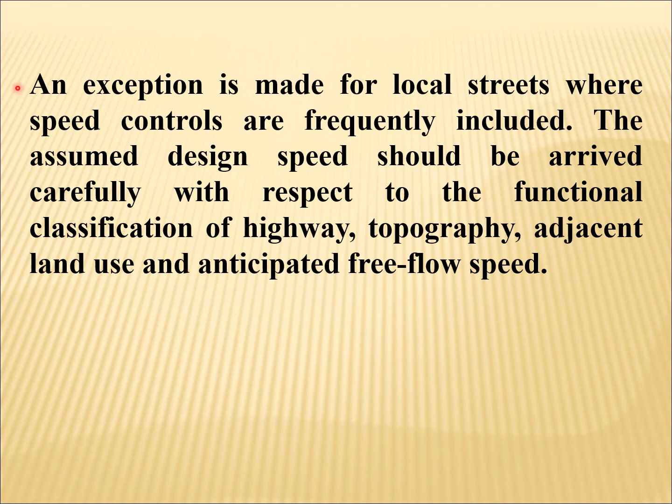An exception is made for local streets where speed controls are frequently included. The assumed design speed should be arrived at carefully with respect to the functional classification of highway, topography, adjacent land use, and anticipated free flow speed.